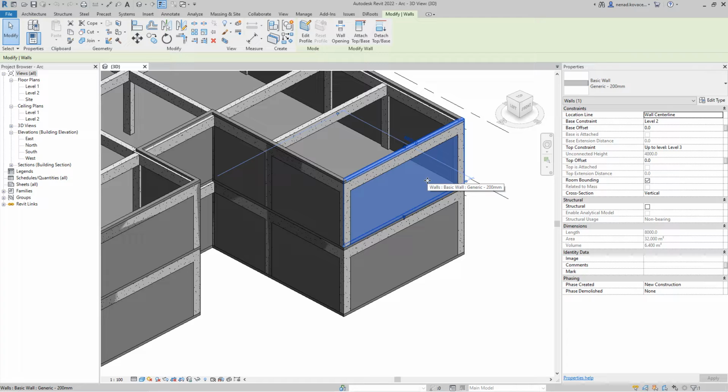The purpose of this script is for you to learn the methodology, and then you can continue playing with this script to scale it, so you don't need to click on elements. You can select some portion of the elements or create a script that automatically cuts all walls with structural elements.